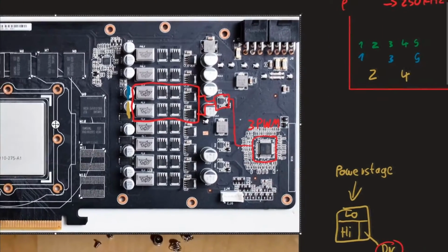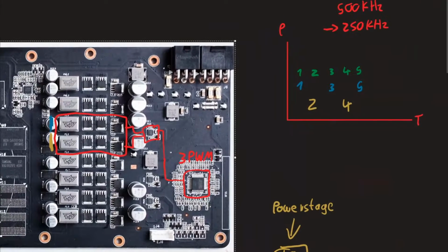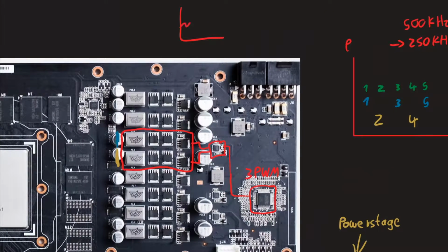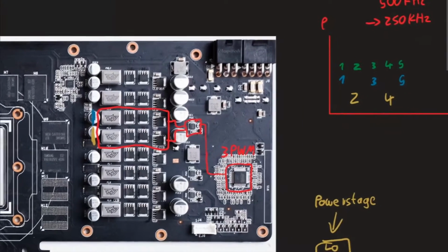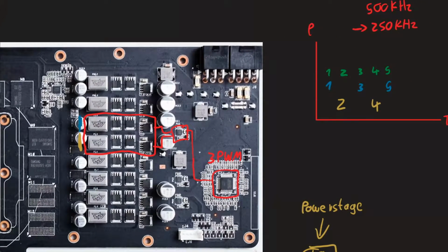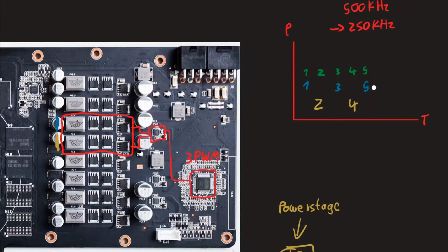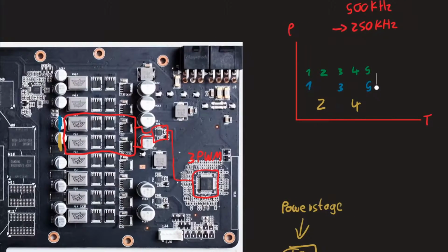If you know how VRMs work and saw a diagram that looks like this, basically, if you know what the voltage put out by a VRM looks like, you will see that this is actually pretty close to an actual 6-phase VRM. There are some trade-offs: you get worse transient response, you have more complex circuits with more failure points, and it gets more expensive. But it is a pretty effective way if you don't have enough money to put a high-phase PWM controller on something, but you want more phases than that controller can support.